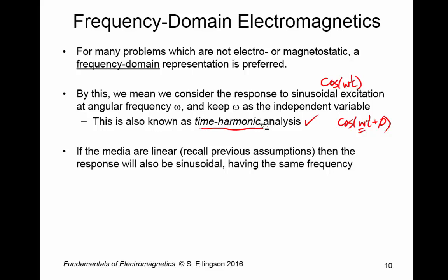If we can decompose problems into superpositions of sinusoids, then we can take those sinusoids one at a time and run them through the system, find out what the response is at that frequency, and then we can put together all the results. That's superposition. So it's a very powerful idea.